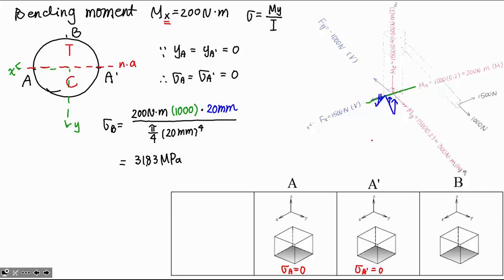Are we going to draw this tension on the side face, top-bottom face, or the front and the back face? Always remember, stick to your cutting plane. On the cutting plane, it is the bottom, so we are going to draw the stress in the Z direction. Okay, so we still have one more force to go.